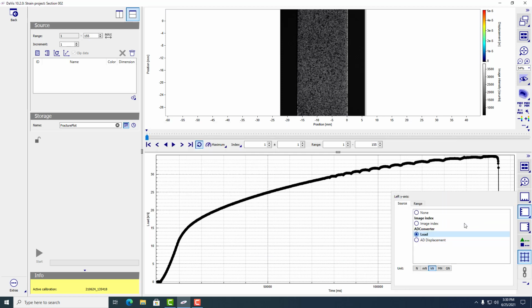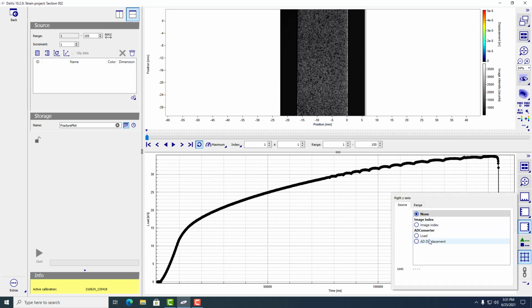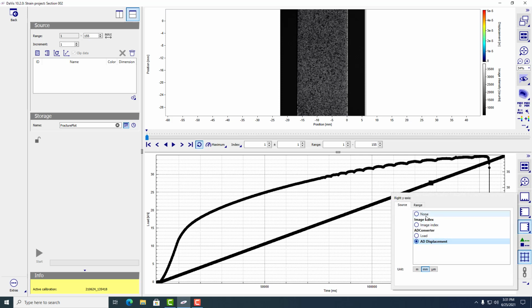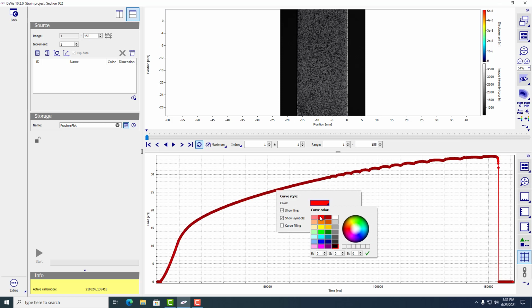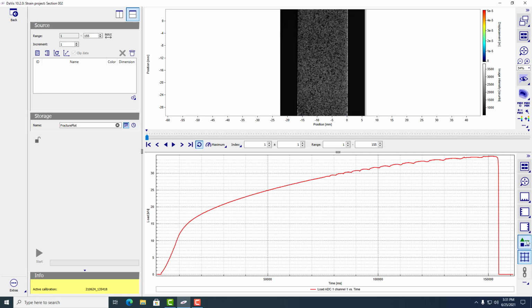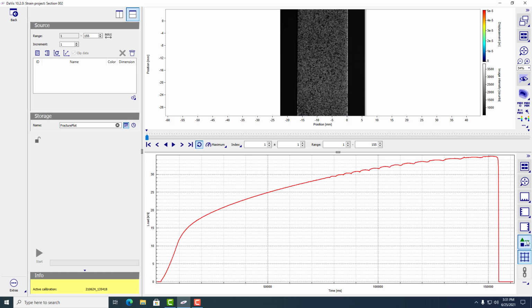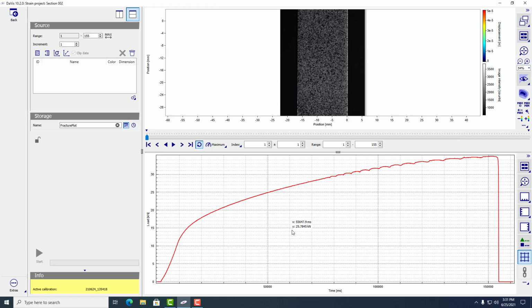Alternatively, click on the left or right y-axis setup tool along the right column. The x-axis may be edited in a similar manner. The curve may be configured by right-clicking on any associated data point. Toggle visibility of the line or symbol and/or edit colors in the pop-up window. Click elsewhere on the plot to close the window. Additionally, a legend may be displayed along the bottom. The Grid tool toggles the visibility of the grid.